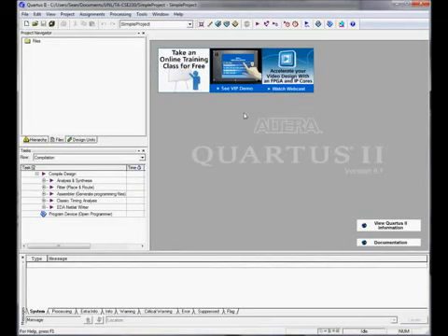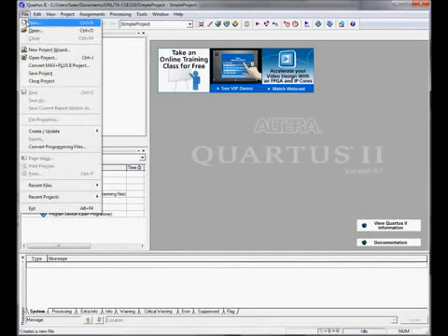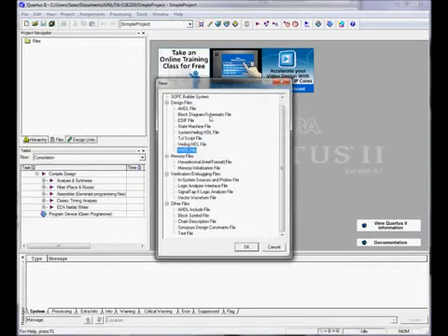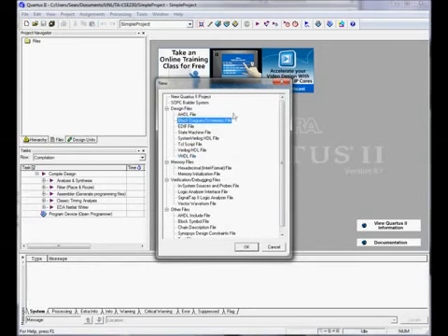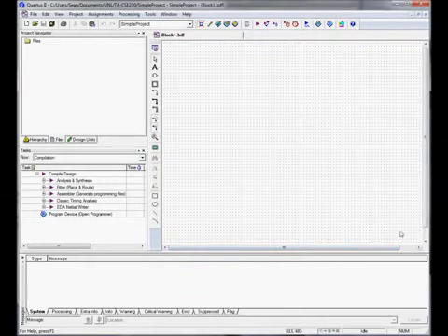Okay, so we've got nothing now. Completely blank. Okay, so let's start working here. We'll go to File, New, and we're going to create a block diagram schematic file. It's here underneath Design Files. It's just in this drop-down. And that gives us this right here. And this is basically, think of it as an architect's design for computers, or for our FPGA. And this allows us to put down all of our different models that we'll develop, either in VHDL or in schematic capture. Right now we're playing around in schematic capture, which truly allows us just to draw right on it. So let's start some drawings.